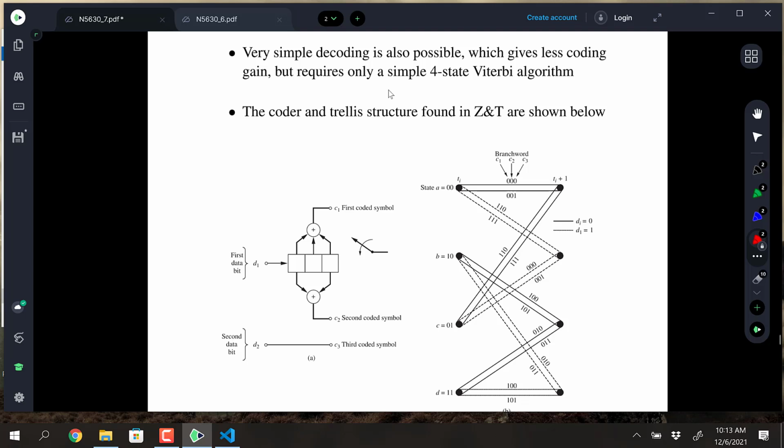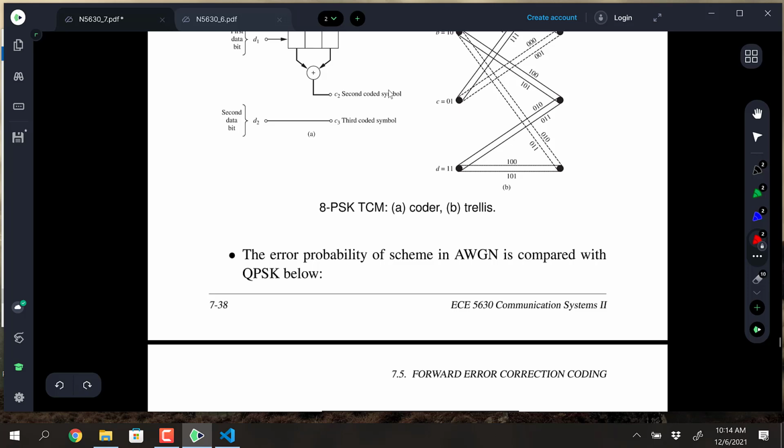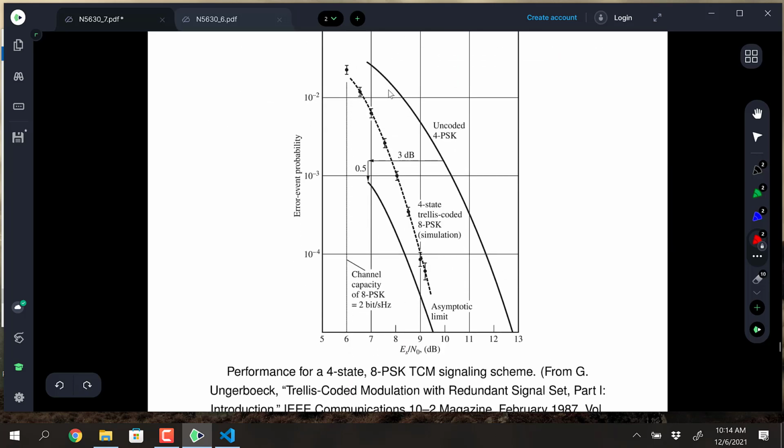You see you have a shift register that takes in 1 bit, and then for each bit in you get the taps there on the shift register. The upper and lower taps give out the coded symbol, and then you have the uncoded symbol that's coming in. But then you have a decoding process which is very efficient with the Viterbi algorithm and another mechanism, and I don't remember the details. I know I implemented it in code though, and it worked and it did well. I developed it in M code. I think I did it in Octave for this company, and they converted it to C code for their software-defined radio, or C++.